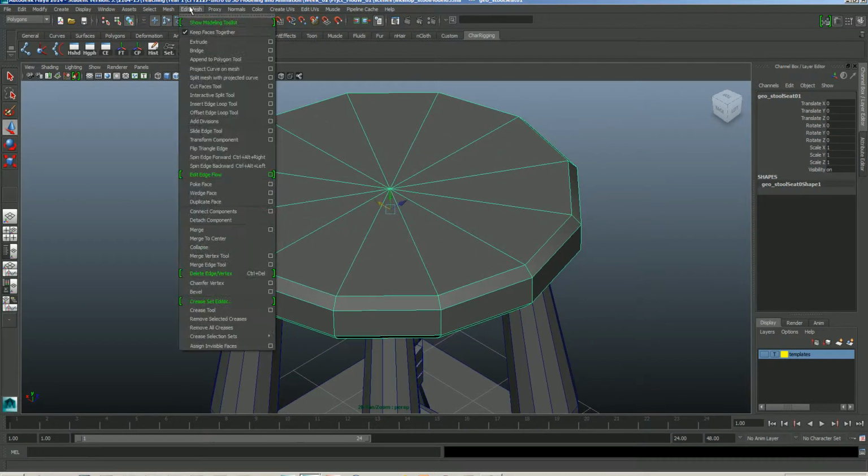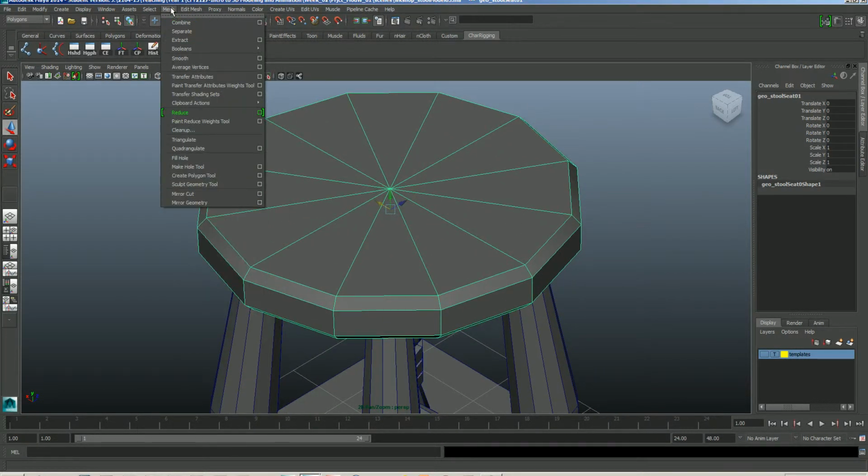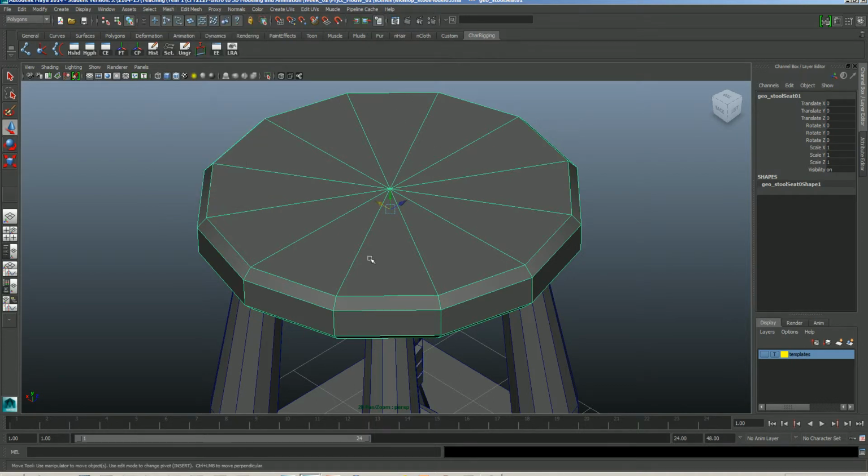We could triangulate, we could tessellate this mesh, we could smooth it out, we could do a number of different things, but these actually add to the mesh itself, and it's nice to have control over this low poly mesh and then create a high poly mesh from that. And there is a way we can do that. We can actually do it with subdivision surfaces.